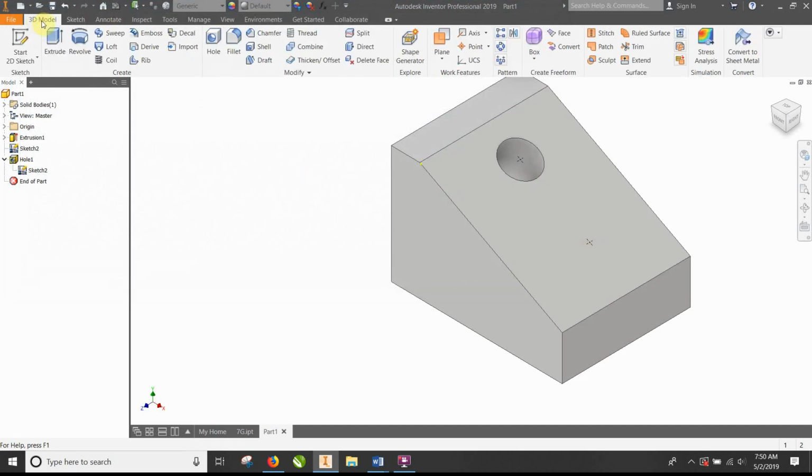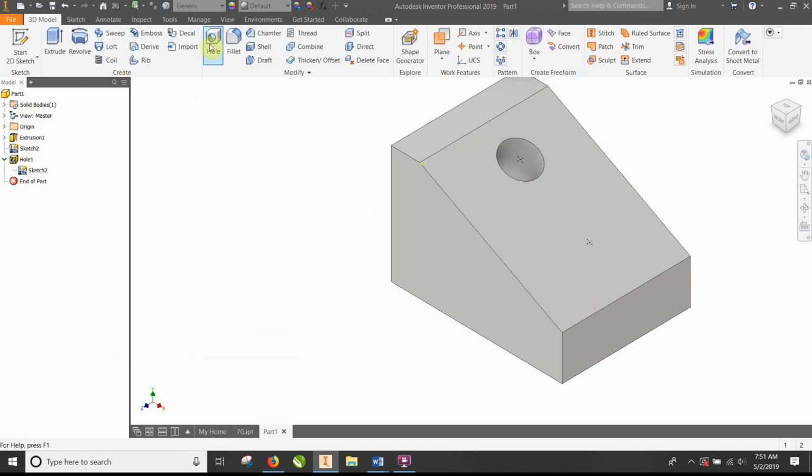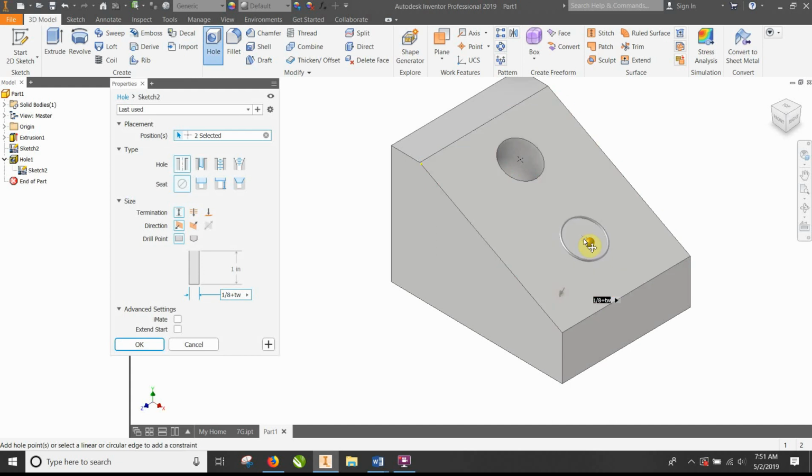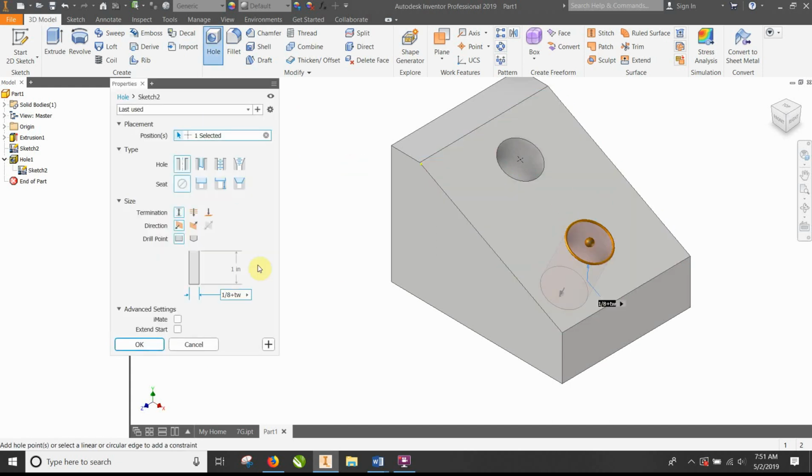All right, let's go back, finish that hole. I'm messing up here. I don't know what I'm doing. Okay, so hole. Okay, I don't know why it's doing that. Okay, hold on. I'm doing something wrong. Okay, there we go. And now we can use the upper hole diameter. So it is the upper hole diameter, UH, we just made that, minus 1/16. All right, and you could put that in decimals or not in decimals. This does have a termination.